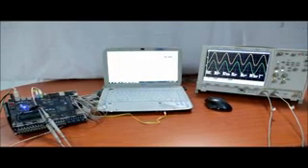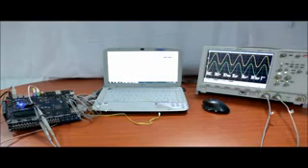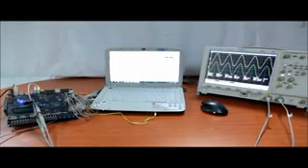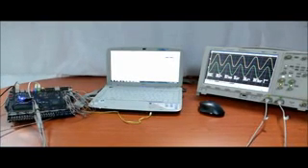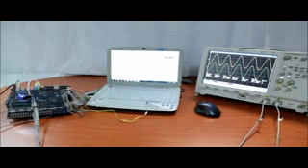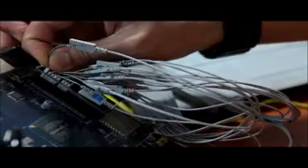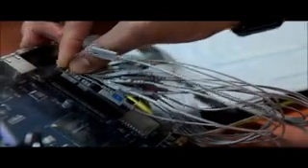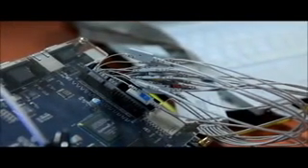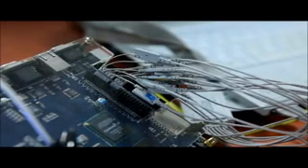We can also observe the quantization effect by using an actual mixed signal oscilloscope. Use the mixed signal oscilloscope to capture the audio input and compare with the audio output after quantization. Connect the 2x8 flying leads to the DE2 board expansion header pins. These header pins are used to observe the digital data from DE2 board. Connect the MSO analog channel 1 to the right channel of line out and analog channel 2 to the left channel of line out.